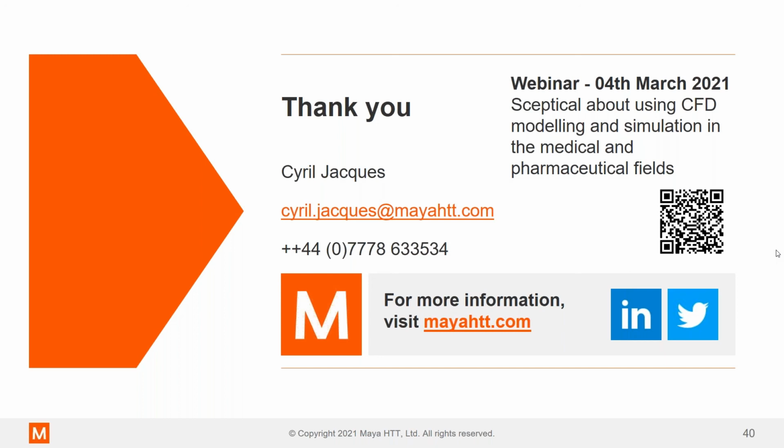But yeah, this is definitely something that's available in STAR, and not only for the VOF. AMR, sorry, stands for Adaptive Mesh Refinements, for those who wouldn't know. So it refines the mesh as the simulation goes through based on certain criteria. For the volume of fluid model, we've got one based on the free surface, and we've got three others, which are for the mixture multiphase, for the overset mesh, and the combustion models, so for the flame front.